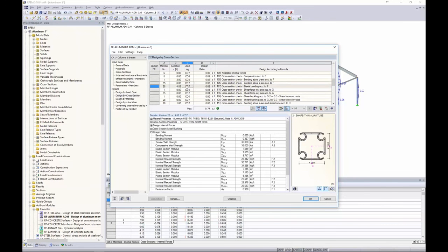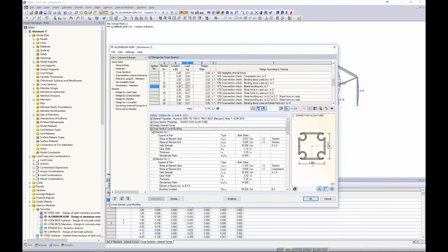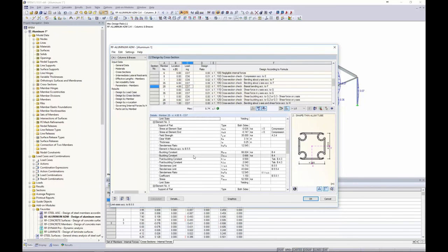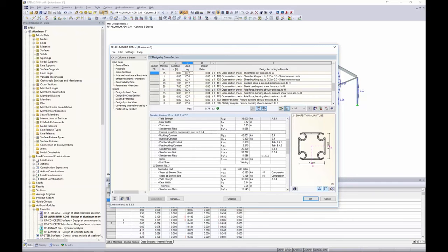Here's our shape thin section, and just like what I said, because we brought in those C sub T elements, here is where those individual elements 1, 2, 3, and 4 are all being checked for local buckling. So that's, I think, a very powerful feature that we can bring in some type of custom cross section and still check something like local buckling.